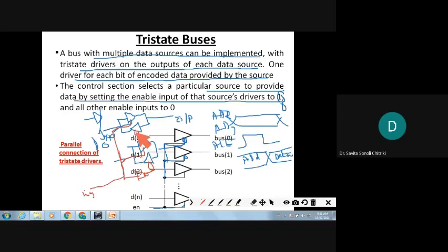It enables these. All this is enabled. So like this, now the tri-state buses bidirectional, we call them bidirectional tri-state buffers, bidirectional from both sides. What you see here are all unidirectional. So in multiplexed address and data buses, bidirectional tri-state buffers will be working.